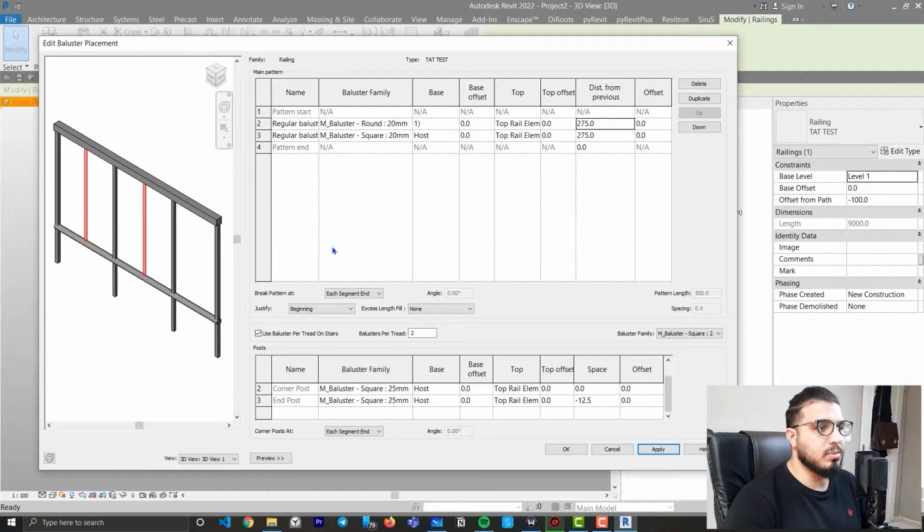and I will put some examples to show other parts of railing and other shapes of railing you can create, and you can practice with them too. And then we have our posts, and for the post you need to specify which part of the rail you want to place posts. For example, I've specified I want the post on beginning, and this is the justify for the offsets in here. And also I've specified that I want my balusters in end and also in the corners.